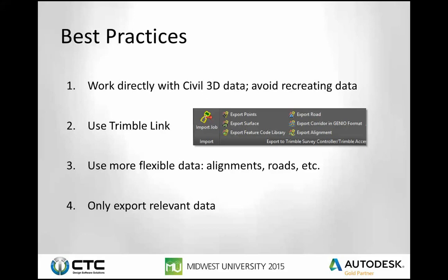And only export relevant data. You know, we're pushing this stuff from powerful workstations in Civil 3D to a small data collector. So don't just send everything out. Try to trim it down to what you're working with.